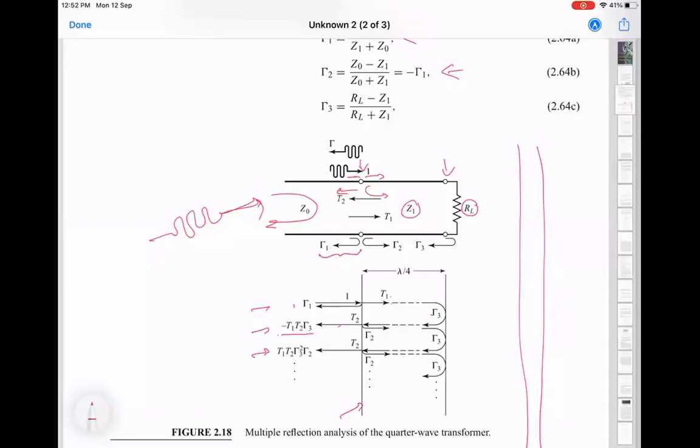So you can think of a starting of a pulse which starts at a particular time, even if, let's say, the frequency was exactly 6 gigahertz, means that initially you're going to get some reflections. But if the signal stays on for a long time, then it starts approaching the situation where it's a pure tone.